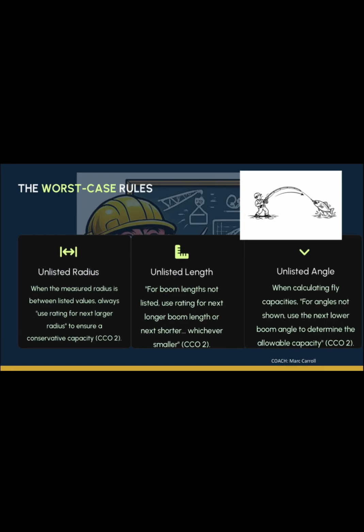Radius inherently increases when the boom deflects under load, or if the load swings out dramatically. Things like you're not over the top of the center of gravity of the load, you're swinging too fast and the load will kick out, or you're going from a high spot to a low spot in your terrain. Never estimate the radius. Always verify and measure prior to initiating a lift. If your radius indication is wrong, you need to pull tape. Get out of the cab and pull tape.